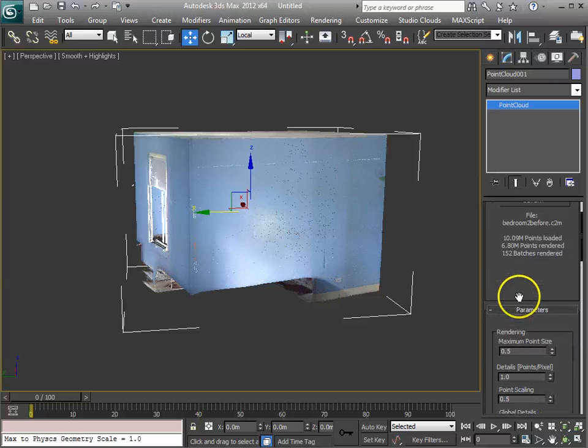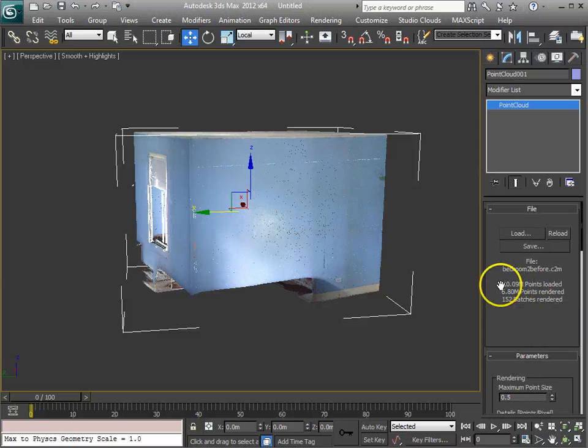The reason is that it keeps the original number of points in here. So if you want to update the points and rebuild the normals, anytime you do an editing function on the point cloud, just go down when you're done and hit the rebuild normals, and your display up here will all be updated. Okay, so that's the edit box.